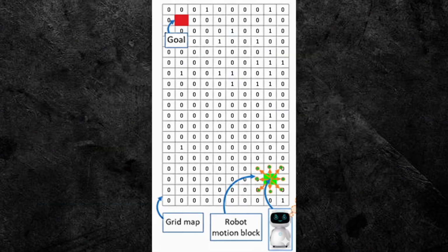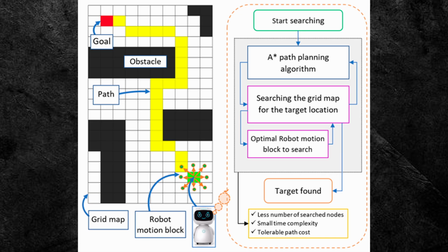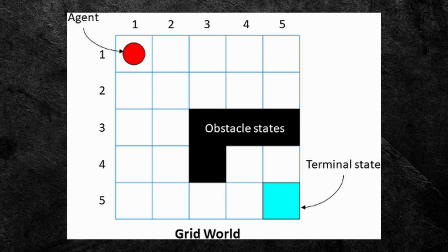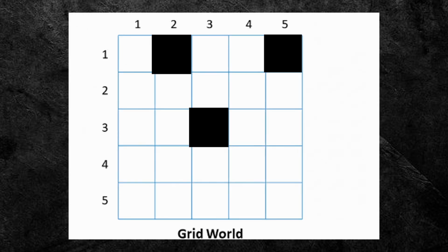mounted on the robot. So 0 means that this cell is free, so the robot can move freely here, and 1 means that cell is occupied. It means that we have some kind of obstacle in our path. Actually, the robot uses this kind of grid map to plan the safest and the shortest path by avoiding collisions. Now let's build our own 2D occupancy grid map in Python. We will first create a grid, then we will add some obstacles, and in the end we will visualize it.